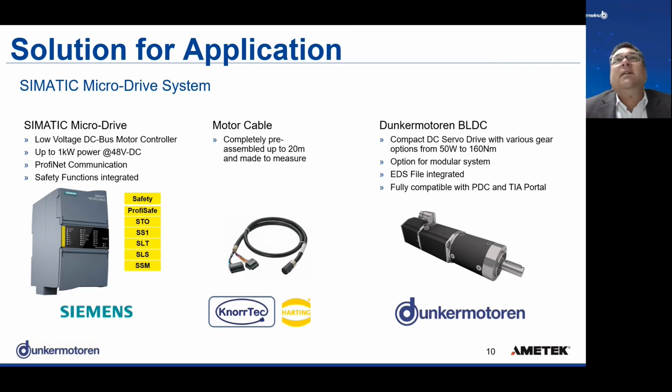As a communication and information, an EDS file is stored in the motor, which the controller can read out and the customer can use to pre-program the MicroDrive controller to avoid the tuning, which is usually needed when you operate a motor on a controller from a different manufacturer. In this case, this tuning is done already and the major parameters are filed here.